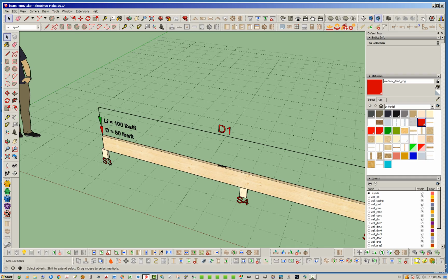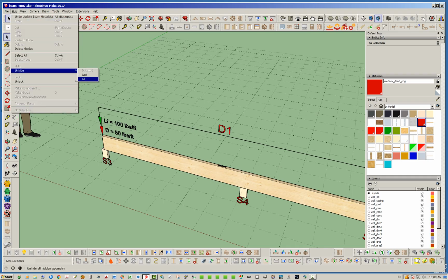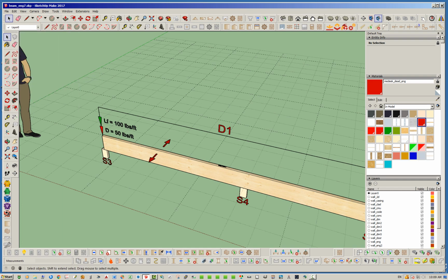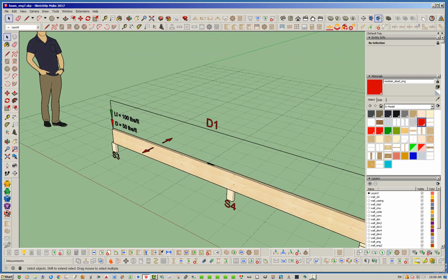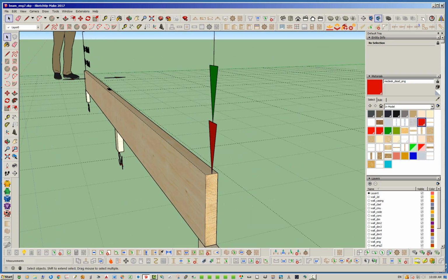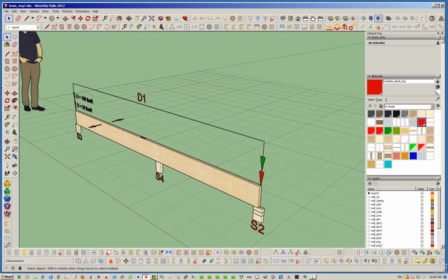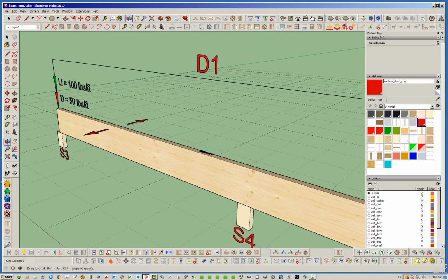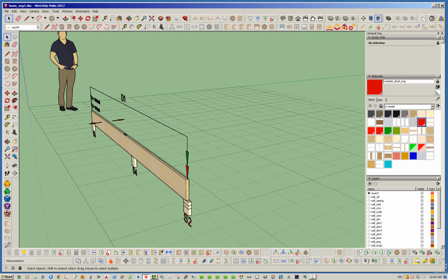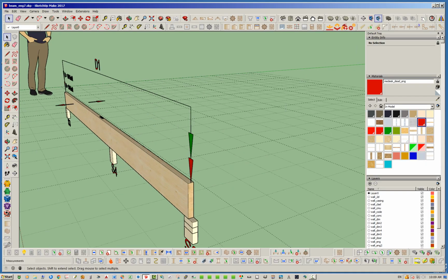So what I mean by that is I'm going to go ahead and unhide a little diagram I show here. So typically when you load a beam like this in what's called the strong axis, along the depth of the beam, this is called strong axis bending. And as you can see, the beam is going to have a propensity to be stronger in its depth than it will be in the much more narrow lateral direction, right?